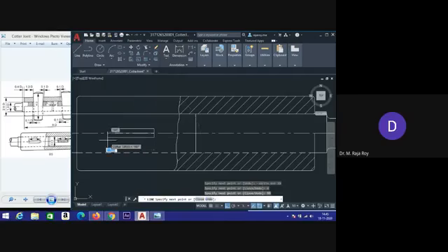This is 39. This is 4.5 mm again. Something like this portion I have completed. After that, complete these arcs. Draw these arcs using the 3-point arc command, by taking some rough distance like this.